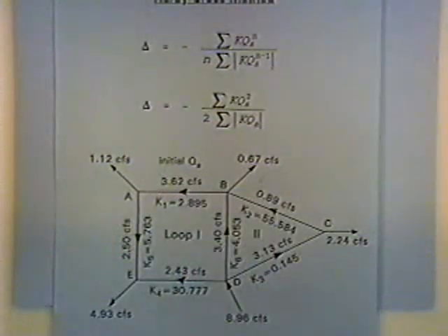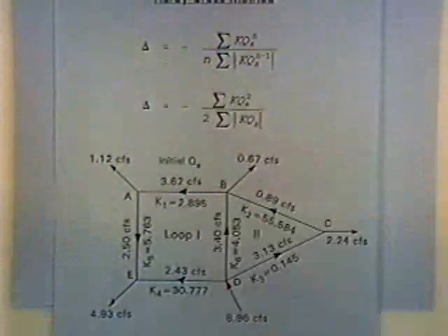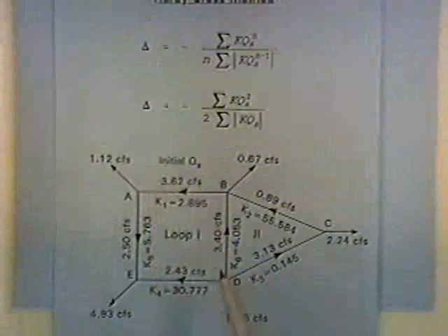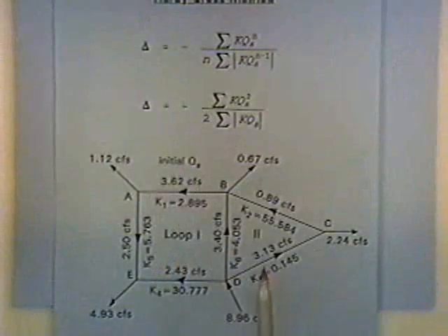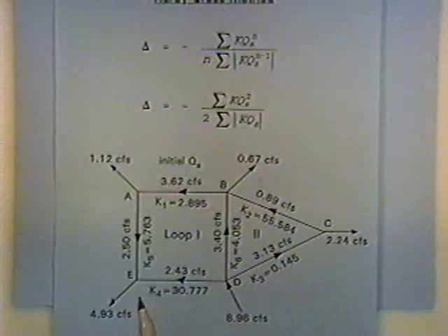They're off by some amount, and the Hardy-Cross equation lets us estimate the correction loop by loop. Now, as we estimate loop by loop, the correction factor is not going to be quite right because you cannot ignore the other loop. But to make the computations tractable in the Hardy-Cross method, we apply the equation to each loop independently of the other.